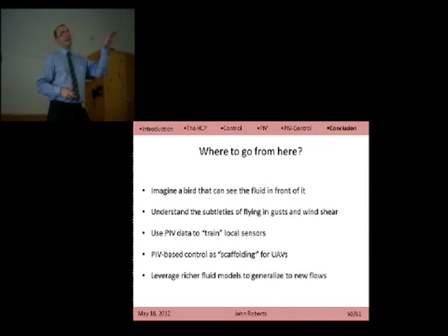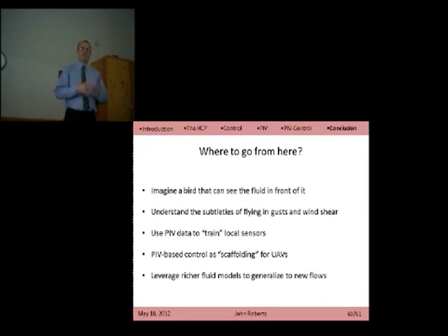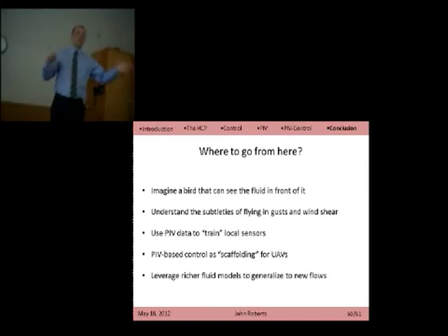So if you can actually design these controllers, design a compensation controller for a gust of wind in this actual dynamical control sense, then you'll be looking at it in the right way. You'll be looking at the subtle dynamical interaction between the body you're controlling and the flow, as opposed to doing a study on a bird and then trying to make your robot bird do the same thing. You actually can make your robot bird do the right thing in the right context, which is this dynamical interaction with the fluid around it.